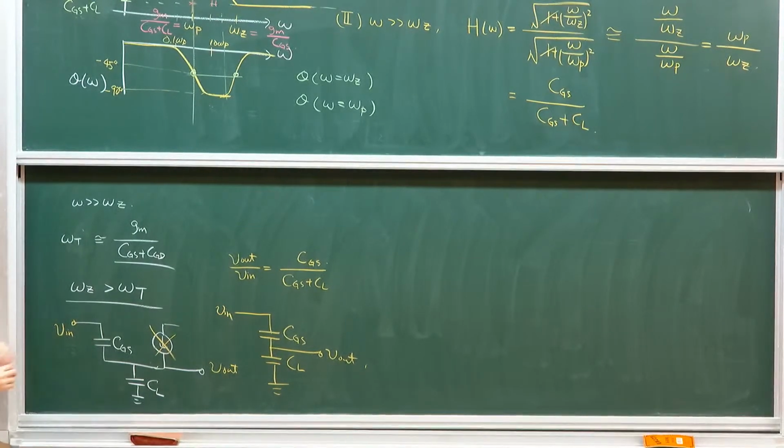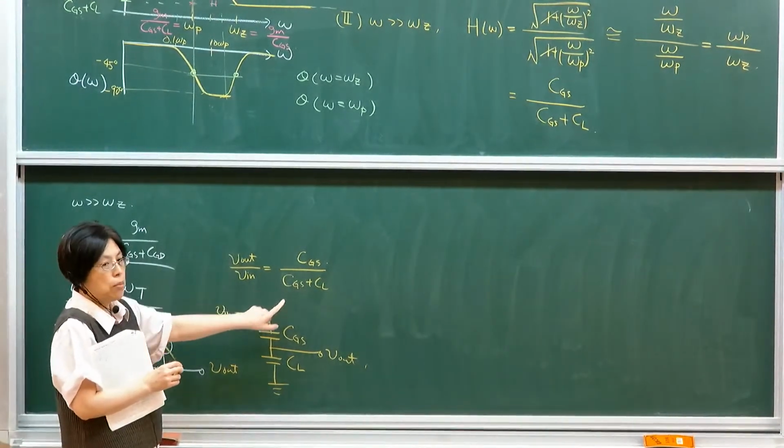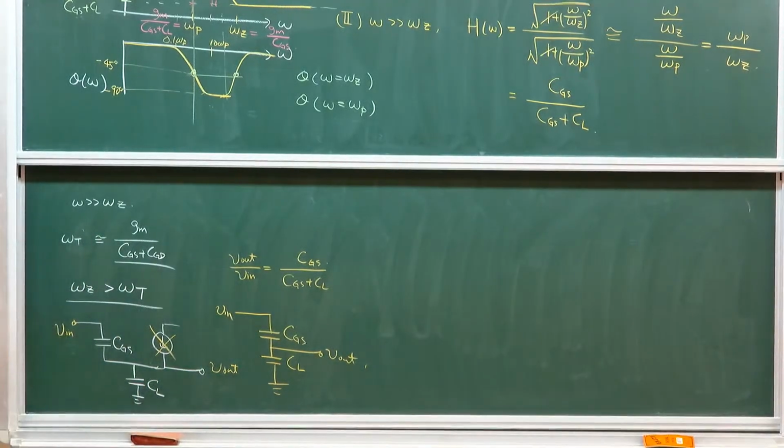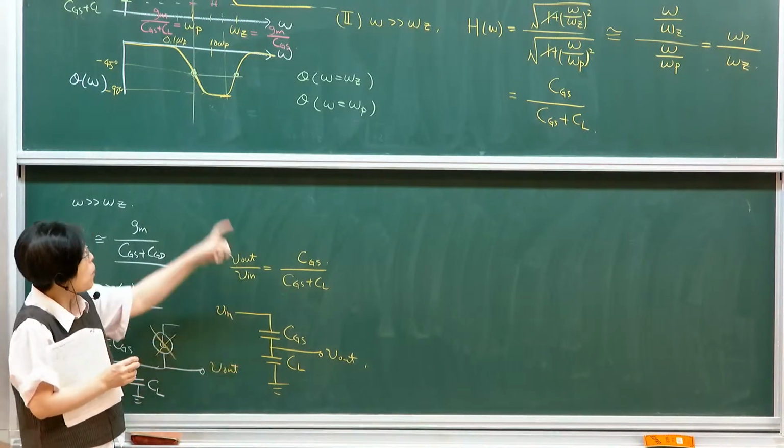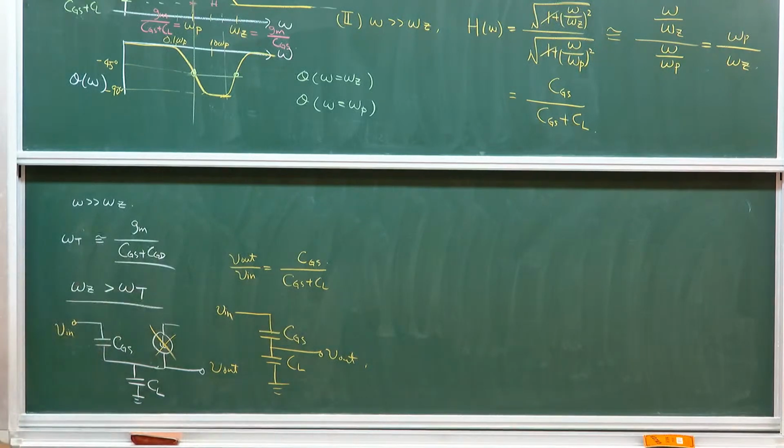So the capacitance coupling effect will simply give you this, meaning that your transistor will only become a coupling capacitance, rather than having an active function, because it's way past its operating frequency. You only see this. That's why in the extreme, you only see the parasitic capacitance effect. It will be a capacitive coupling network, if you like.